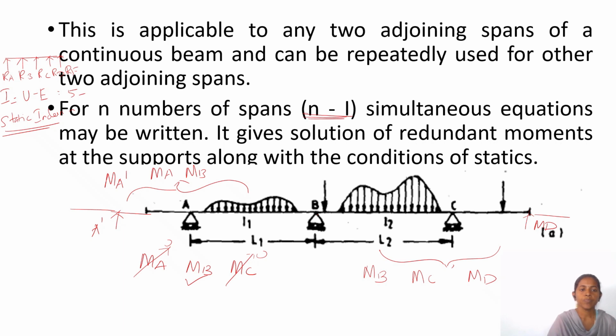Normally we have 2 equations for a beam, because if there is no inclined load, all the loads on the beam are generally perpendicular. So we can neglect the summation of Fx equal to 0 equilibrium equation, and only consider summation of Fy equal to 0 and summation of moment equal to 0. That's why the number of equilibrium equations is considered to be 2.